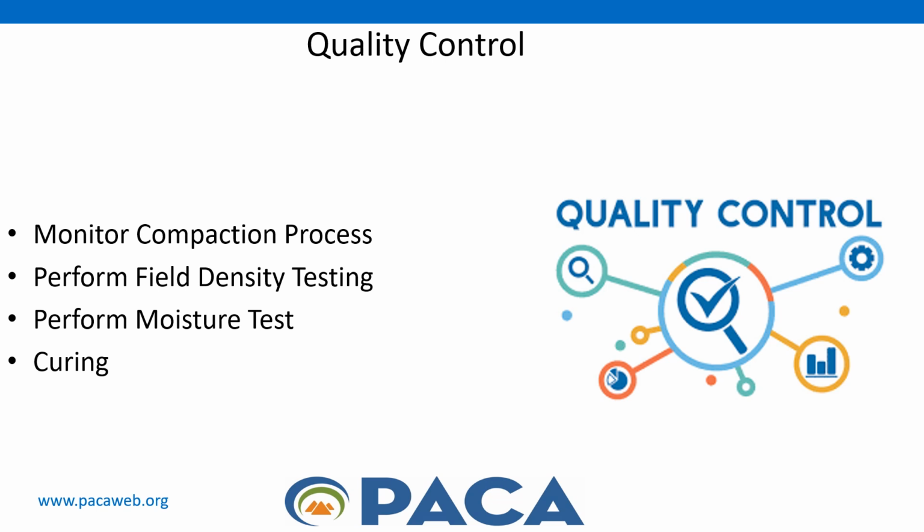The field density testing should be performed during the construction in accordance with approved AASHTO or ASTM methods. This will confirm that the project specifications are being met. Consideration should be given to testing for density and moisture on a regular basis, for example, maybe every 5,000 square feet for each compacted lift of material. And lastly, curing should be performed according to the project specifications.